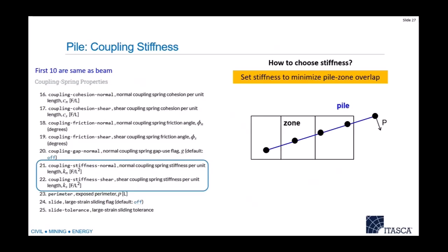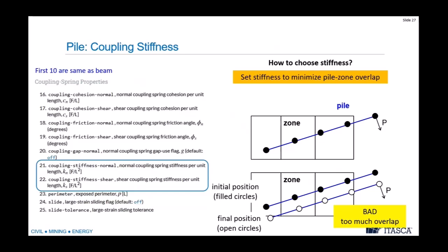You could say, well, I'm not going to worry about the stiffness, I don't care, let's make it extremely small. If you do that, you're basically saying that this whole element, all the nodes in it, can just move through the entire grid with very little resistance. It's great that you have a small stiffness because a higher stiffness affects the time step, but it's not going to be anything close to reality.